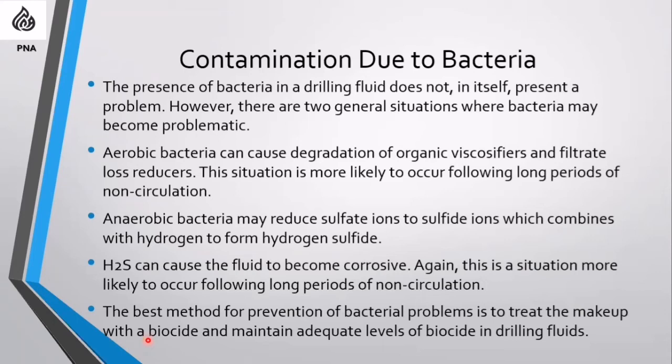In that time, our viscosifier or fluid loss controller may degrade and make some bacteria, and we find our parameters are not as before, because some of the viscosifier or filtrate loss reducer is not working anymore.